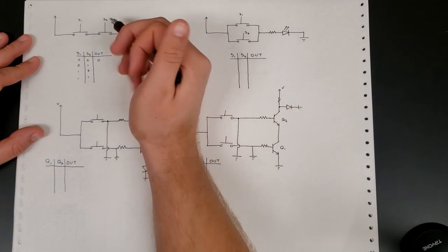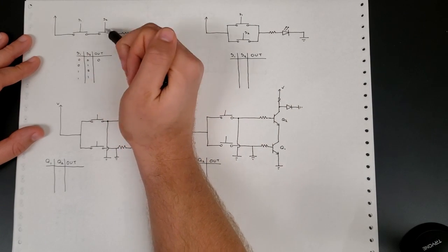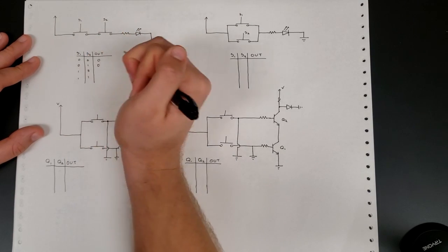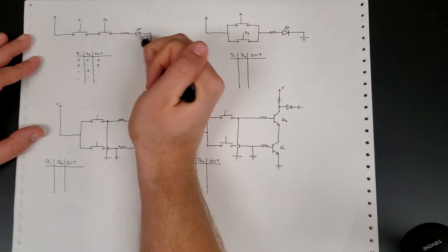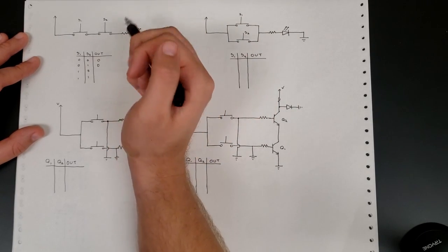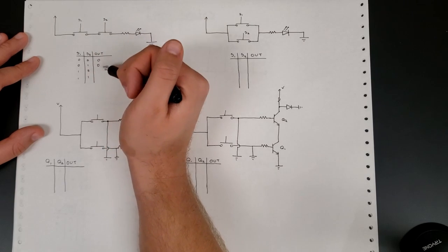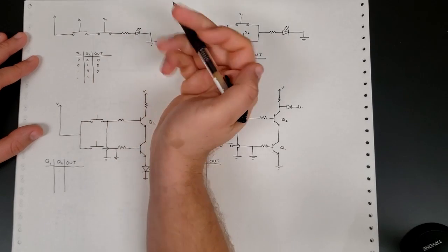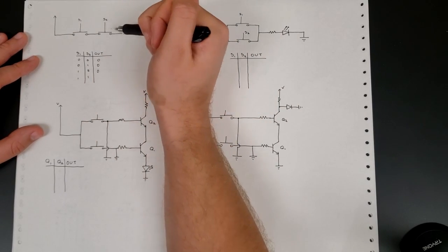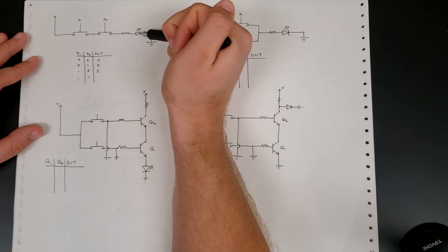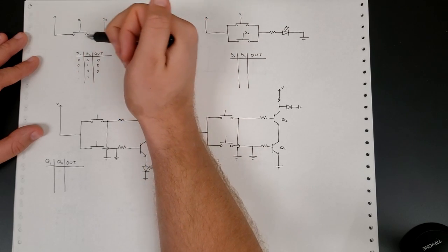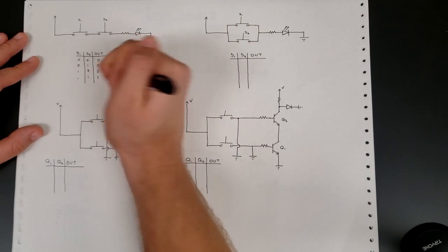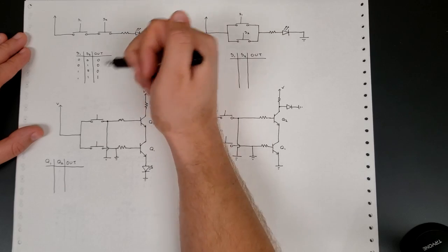All right, now if we leave S1 open because it's a 0 and we press S2, right, the circuit is still broken at S1. So again, we have no output, right, because there's nowhere for the current to flow, so this LED is not being lit up. The same thing goes for the next case, right, where S1 is closed and S2 is open? Since S2 is open, the circuit is still broken because these are in series, and so we still have no output. Now, for the last one, if I press S1 and S2 at the same time, I will now have a continuous line for my current to flow through, and so I now have a closed circuit, and that means I now have current running to this LED. So I do now have an output, or this LED is now being lit up. So then I have a 1.